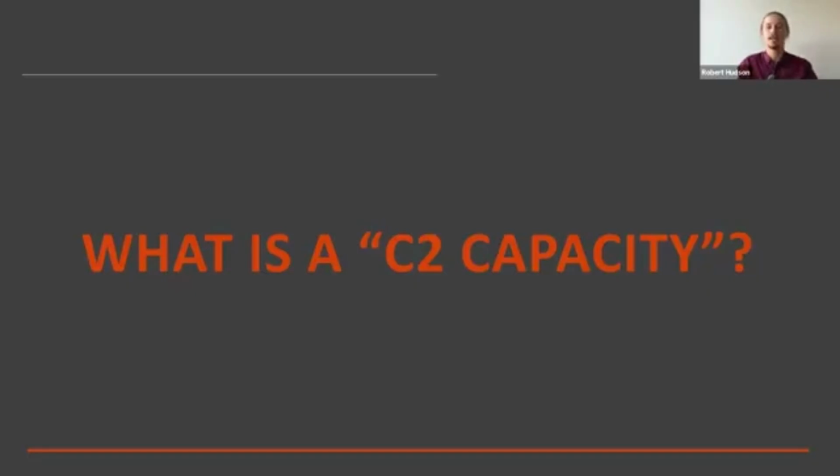A reasonably precise answer would be that a C2 capacity is the expected 5th percentile capacity of a post-installed anchor in a reinforced concrete beam just outside of the plastic hinge zone in a crack that is 0.8 mils wide in a 90th percentile 475-year return period earthquake in Los Angeles. Which is quite a specific thing.